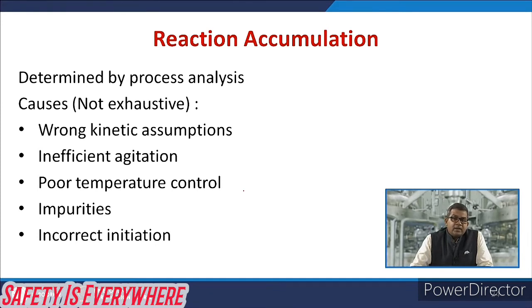And sometimes incorrect initiation may be because of contaminated raw material. Sometimes it may be attributed to poor temperature and pressure control at startup. This may be attributed to the reaction accumulation.